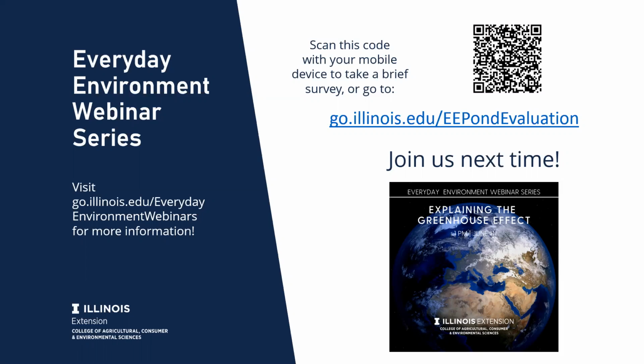That is assuming that is native soil and you've got a little bit of slope coming up from it, because in those cases you're not opening up crevices for water to go around the dam and toward the lower end of it. Now, as you get closer and closer to the dam, there's a zone where you really want to think about keeping them away from it. And I should say that varies a lot by the soil conditions and the layout of the pond itself.